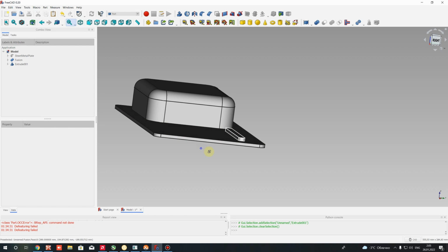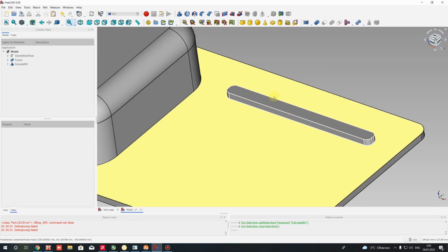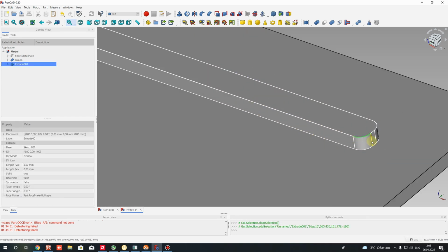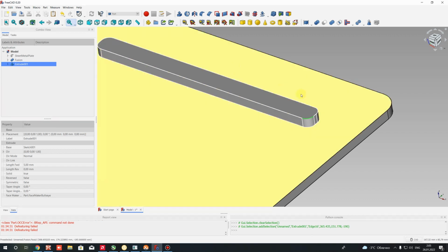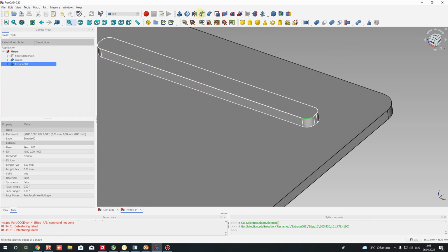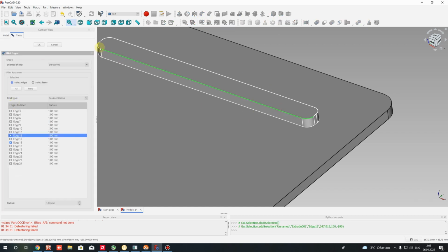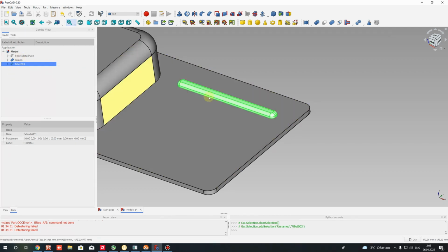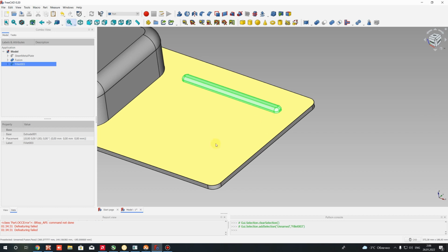We'll get this form rectangle. Okay, so let's make the fillet of these corners for these edges. Let's choose one edge. Let's choose the fillet operation, and let's choose these edges around. Yes, and we have here all edges activated, and let's set the value of radius. I think I will set 3 millimeters, and let's try it. Yeah, it looks good.